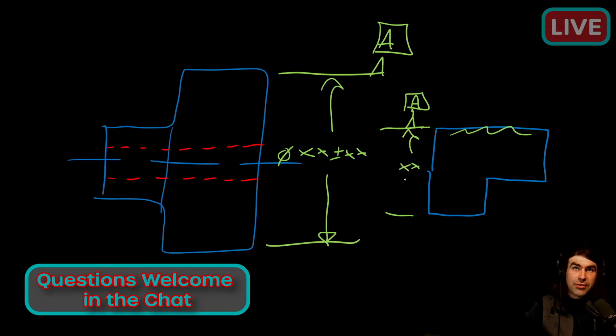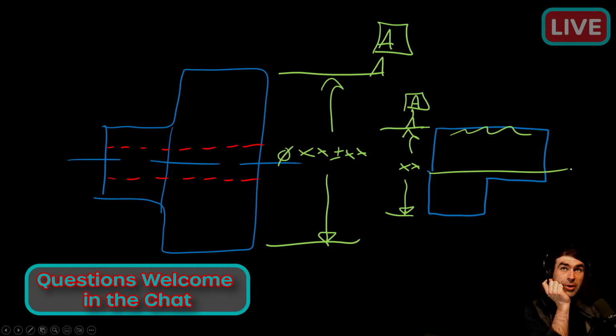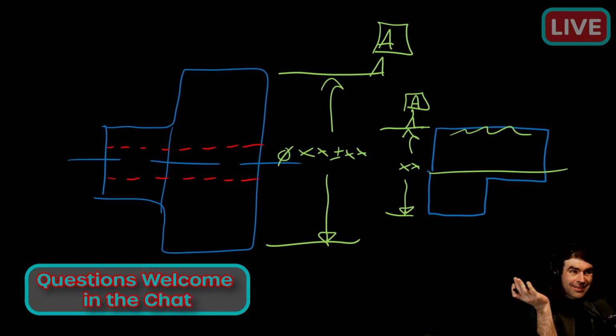If the datum feature symbol is in line with the dimension, it applies to the center of the part. With the cylinder, that's not a thing, right? We can only apply it to make the axis of that cylinder the datum feature. There is no applying it to a tangent line on the outside of the cylinder.